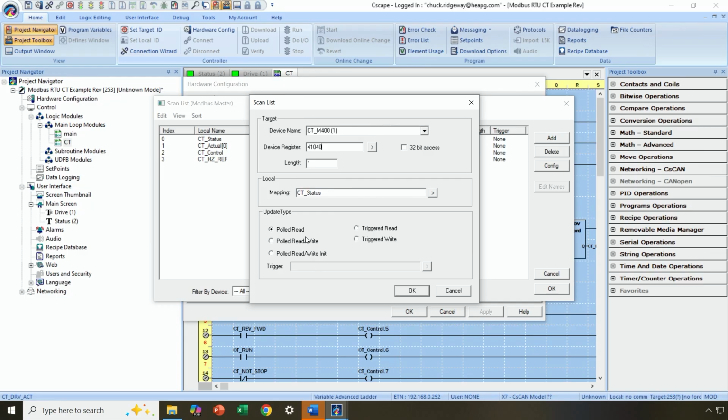Everything works fine. If you've got an especially large list of data that you need to read or write, for some of them, you might want to make them triggered so that they aren't regularly part of the poll list. That will help you keep your scan rate down. So if there's data you don't really care about getting frequent updates on, you can trigger it once a minute or once every few minutes to get a copy of the data.